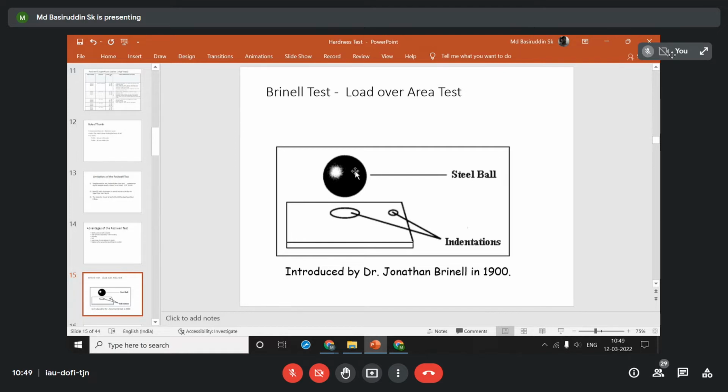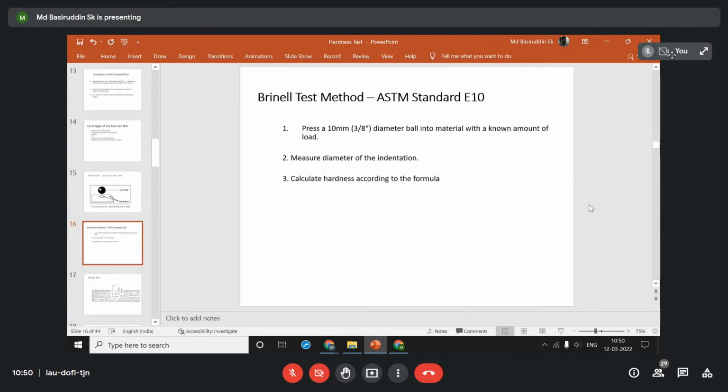So then we have to obsolete that particular test. That means we have to avoid taking the hardness of that particular material. Okay, so this is the restriction for the Brinell test. Now, in laboratory scale, it is very difficult to maintain the load of 3,000 kilo or even 500 kilo. So in order to manipulate the load, Brinell has suggested that